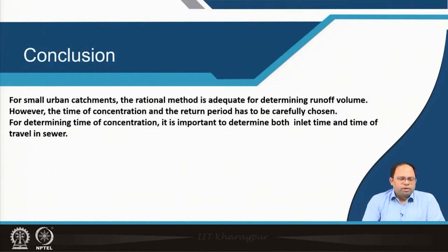To conclude, for small urban catchments, the rational method is adequate for determining runoff volume. However, the time of concentration and the return period have to be carefully chosen. For determining time of concentration, it is important to determine both inlet time and time of travel in the sewer.